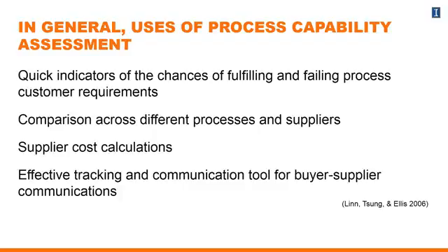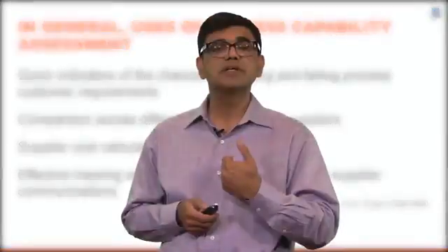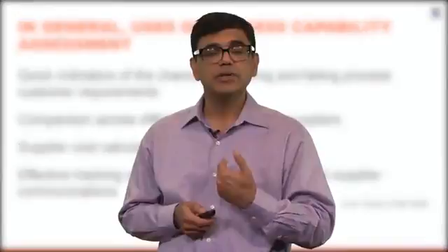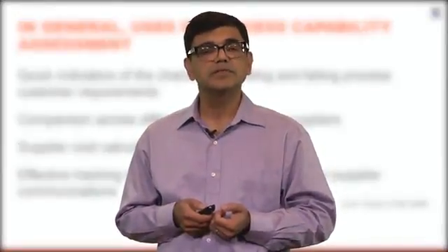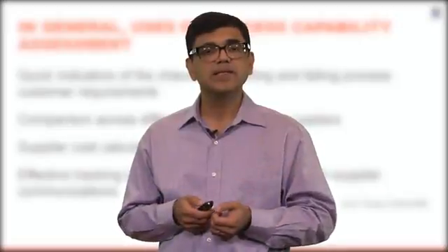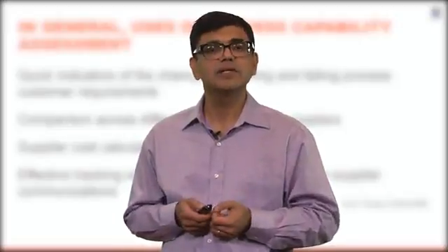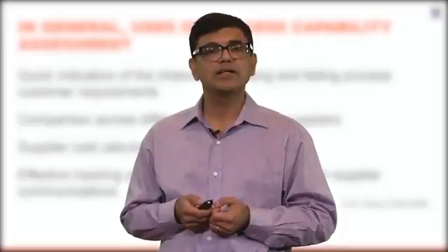It becomes an effective tool in terms of giving specifications to suppliers. You can use this ratio and index to tell suppliers what you expect in terms of the process capability ratio, or the process capability overall, for particular items that you're dealing with.